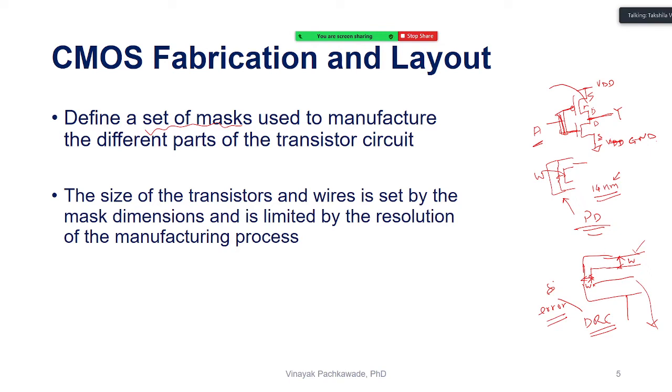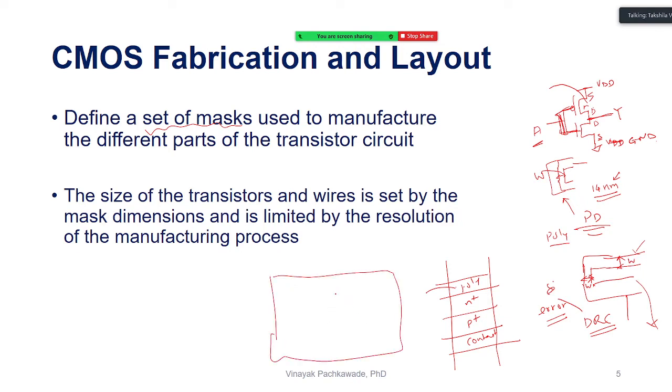Yeah, when you want to connect these two transistors by the polysilicon gate, you will choose the polysilicon layer from the library. In the tool, you will have a box on the right-hand side, and it will show you the different layers. They will say this is layer poly, this is N plus, this is P plus, this is contact. Then you click with the mouse on the poly. You select the poly, and this is your schematic drawing area or layout screen. Then you have picked up two transistors here first, and then you are connecting the gates of these two transistors through this polysilicon. You call it poly. These transistor cells are already defined, but this rectangle you need to draw sometimes. So this width you will choose and you can adjust. As long as you don't violate the design rules already set and predefined, you can adjust. This is in your control. They will always give the minimum dimension.